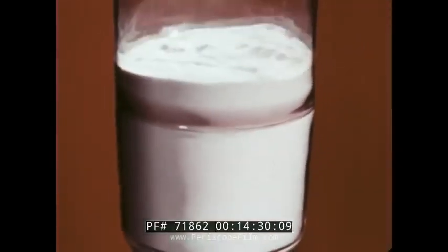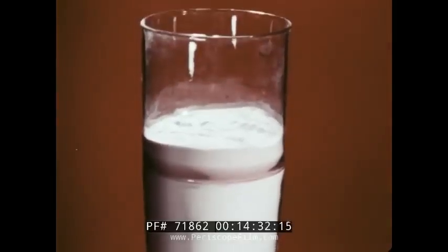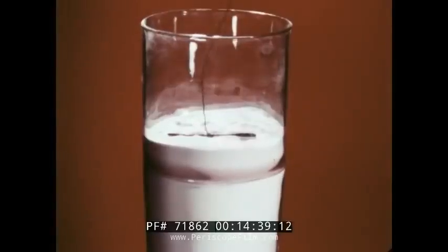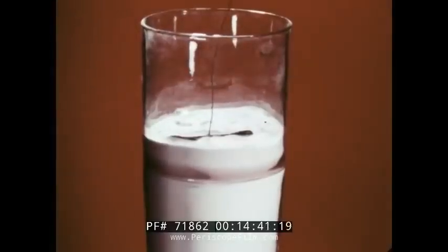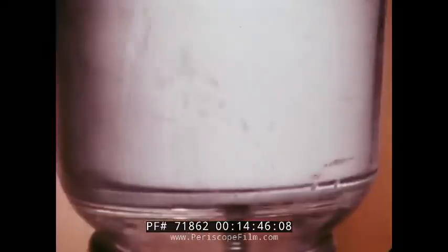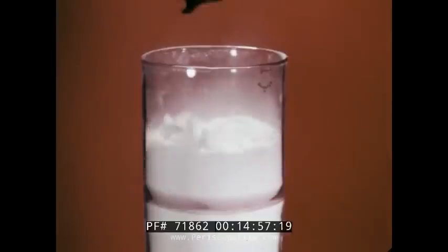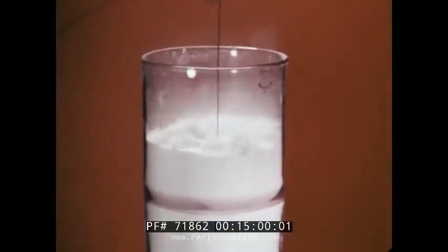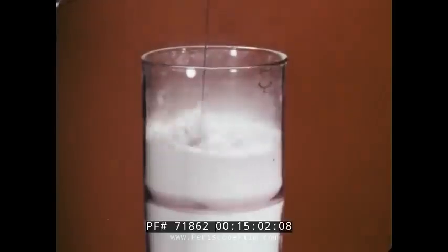The catalyst also has to circulate freely in the cat cracker, and to do this it must be made to behave like a liquid. At rest, the powder is a solid mass and will support a metal object. But if gas or vapor is blown through it, it's churned up or fluidized. The wrench sinks, as if it were in a liquid.